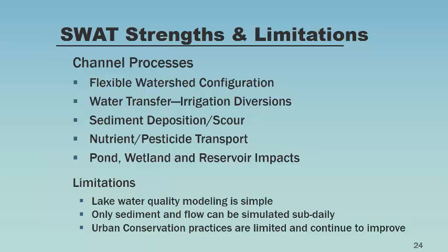SWAT cannot do everything, obviously. It has limitations too, such as lake water quality is not one of the major strengths of the SWAT model. If a lake is part of a bigger watershed that you're studying, you can use SWAT, but if the lake is the end product that you want to study for a TMDL, then you may want to think about bringing in